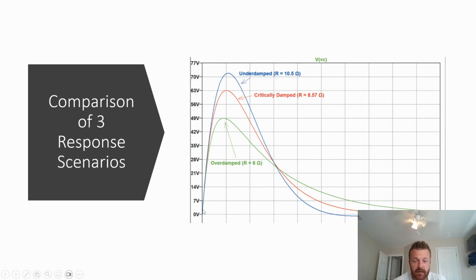When R is small, you'll see an overdamped response shooting up from an initial value of 0 for the quantity that we're talking about here, going to a maximum value and then exponentially decaying down to 0. In the case of critical damping, that is basically the largest you can make R such that this never actually crosses 0. It doesn't exhibit any kind of oscillation.